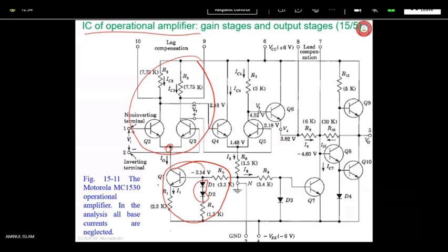Differential voltage. Remember that difference between these two voltage output terminals of the first stage. So this gives you this value, half of hFE R7 divided by hie. hFE is 100 and R7 is 3 kilo ohm, hie is equal to 5.2 kilo ohm. So kilo gets cancelled and you get this value: minus 28.9 is the gain.